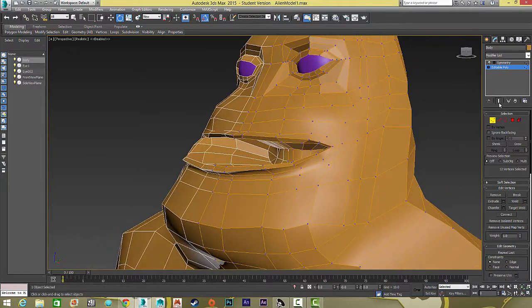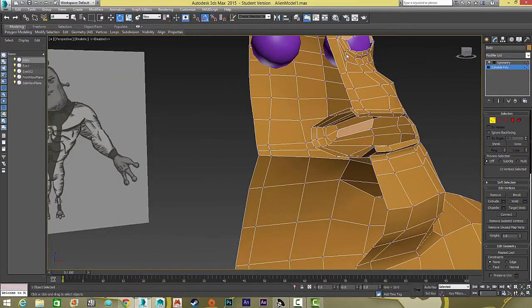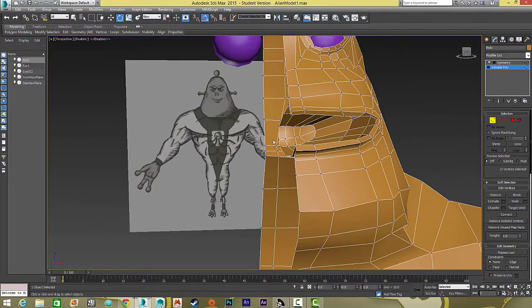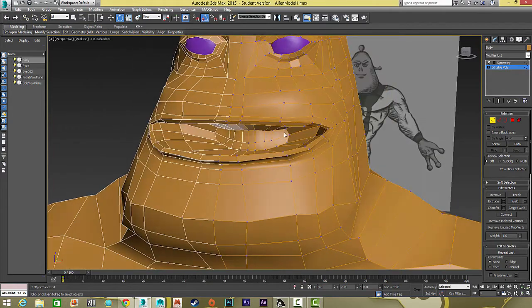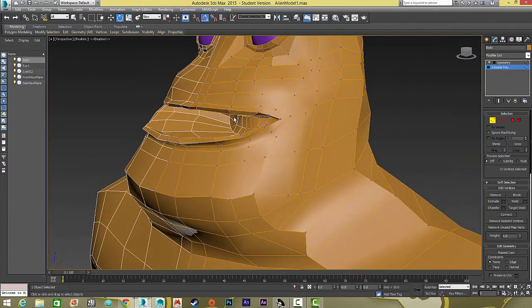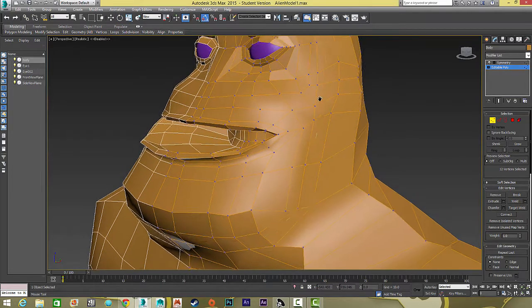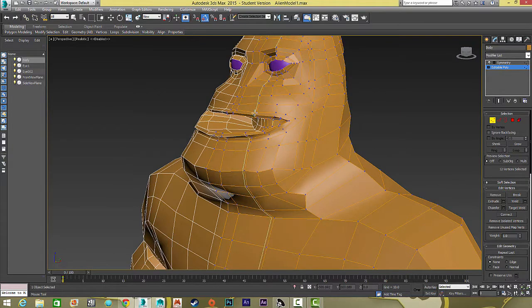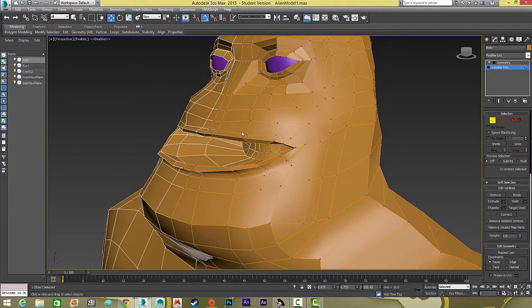We also extruded the mouth in the same way we did the eyes. What I had to do was delete the polygons on the inside, since this is a full symmetrical form and there's not an inside polygon there, but you should be able to see that. Then add a couple more loops, but the main idea is so that we can come back in with the Swift Loop tool and add more loops around the mouth. We can add more loops around the eyes or the forehead. It just takes some time, so you can review this video and review the steps.